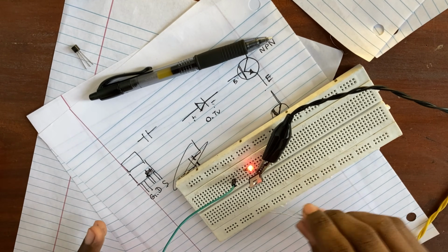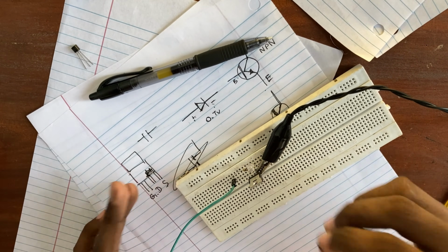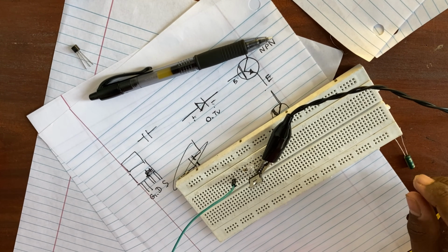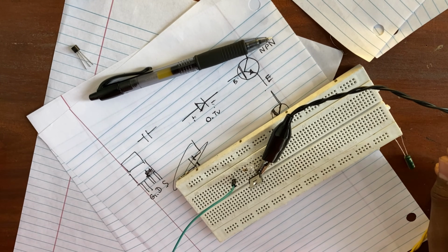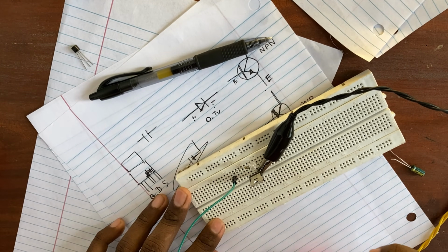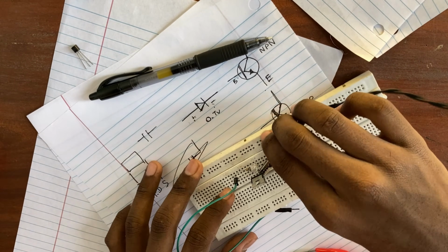So by discharging the gate, I can turn it off. If you are using it to turn something on and off, you will need to add a resistor, like a 10k resistor, through the gate and source pins to discharge the gate pin. So keep that in mind.